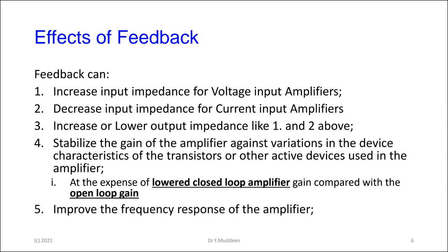And you kind of know that already if you just think about the op-amp specs, that a 741 op-amp has maybe an open loop gain of maybe 10K. But once you start to put the feedback resistors in it, you start to drop the gain down to, you know, maybe a couple hundreds or maybe in the tens and the like. And then, of course, we improve the frequency response of the amplifier. So we'll touch on those.